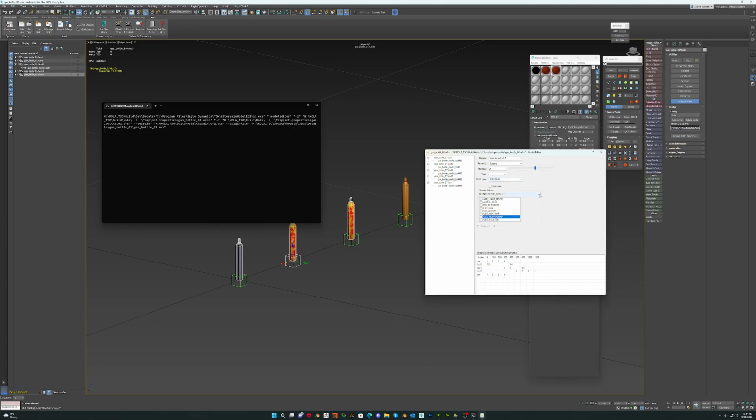Now you can use this blend factor. So generally you would use blend factor scale XYZ. So as you move further away from the model, it scales down in all axes. So it looks like it's getting smaller in the distance. So in this case, we will do that.